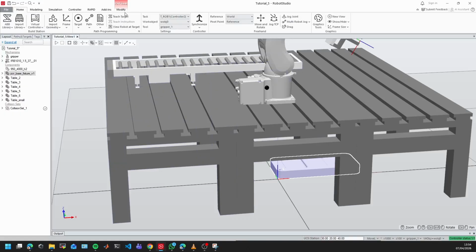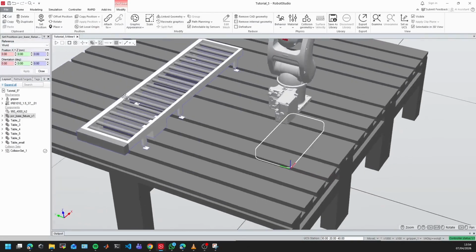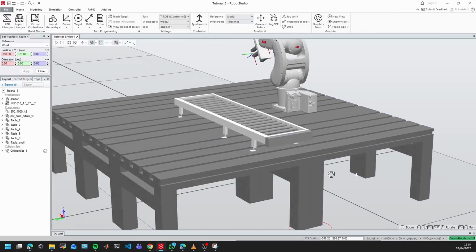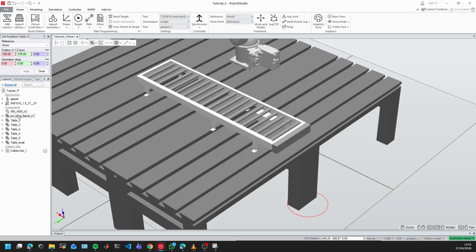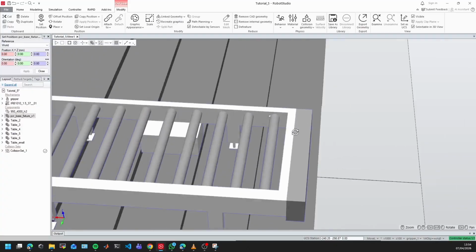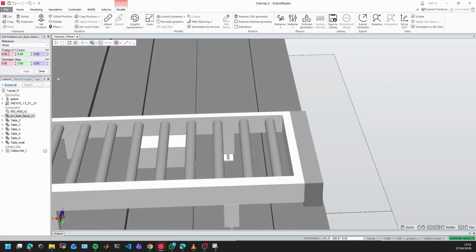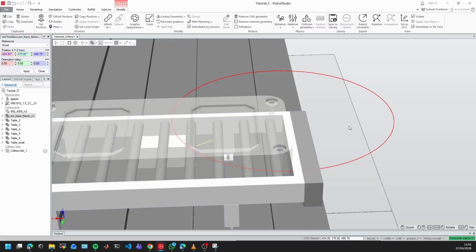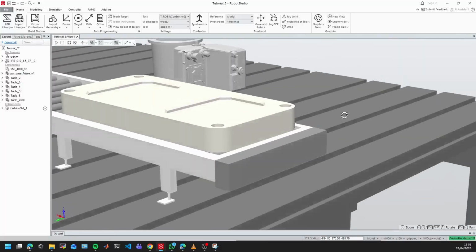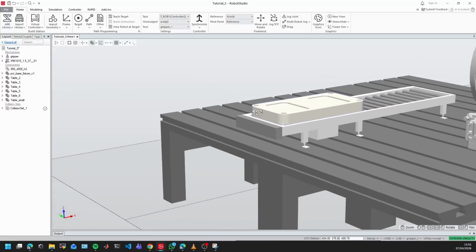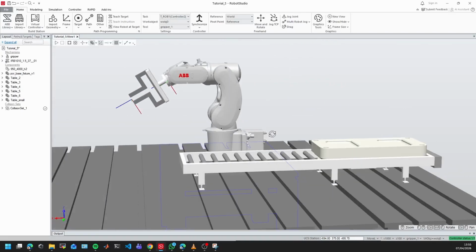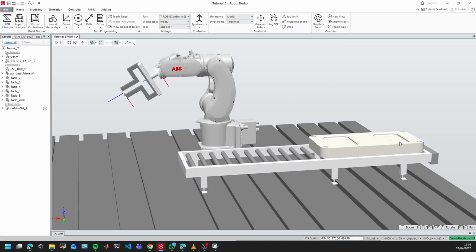So now I have that. I'm going to modify the position. I'm going to select again the PCR fixture, modify, set position, and I'm going to click that corner there. Always remember to click the red square there and the corner there. Apply, close, and now we have it. We have a tray that is on top of my conveyor.